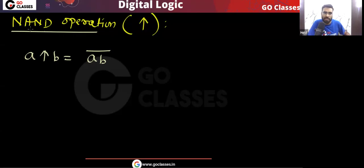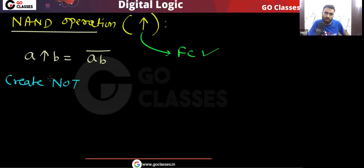Now I am saying that this NAND operation is functionally complete. Okay, so how to prove it? Tell me, how to prove that NAND is functionally complete? This single operation is functionally complete. Very simple. We can create NOT using NAND.